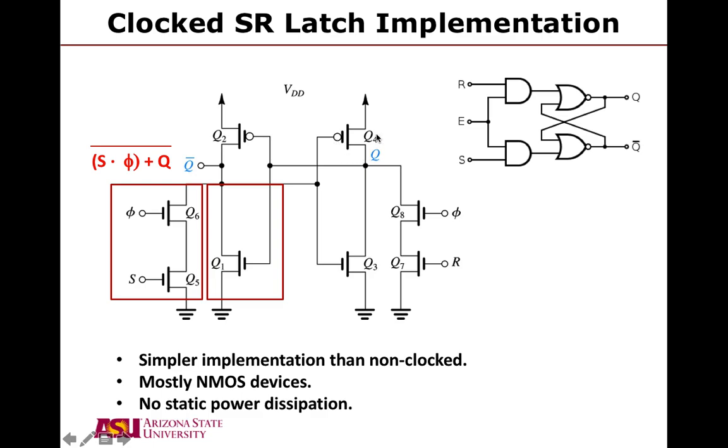Now, the pull-up network, again, is not a CMOS logic gate pull-up network for this case. What has been done is actually an inverter has been combined with this system, and just from the inverter, so if you look, this is an input, this is an inverter, this is an output. So if you call this Q bar, this point here in the middle, then the output would be Q, and vice versa. If Q goes in, this is Q bar. So this has been simplified from a standard CMOS logic gate implementation.